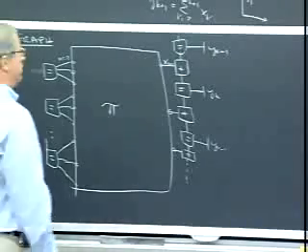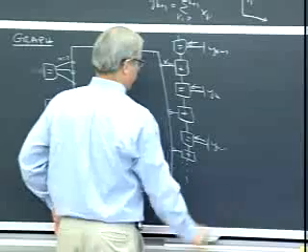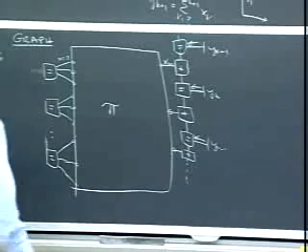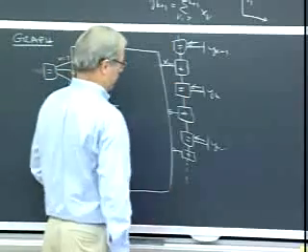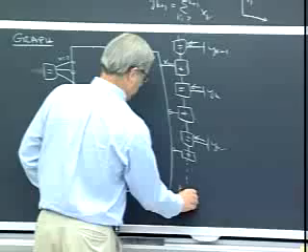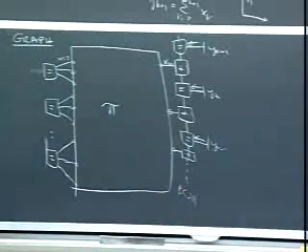What do we see initially? We initially get received data, measured intrinsic information for each of the bits that we actually send over the channel. And what's our next step? Trellis, yeah. We do the sum product algorithm on this trellis. So we just do BCJR, ignoring the fact that it's rate 1. Doesn't matter.